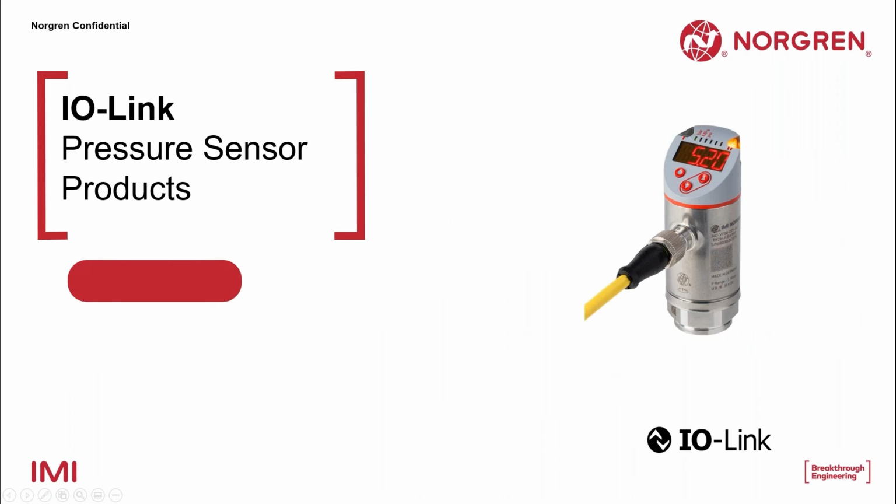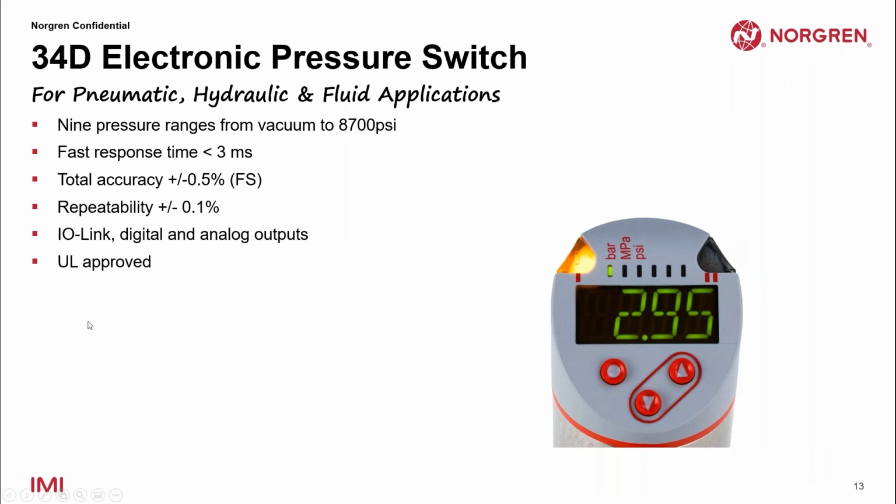Next up is our IO-Link pressure sensors. The 34D is Norgren's electronic pressure sensor and switch. It's available in 9 pressure ranges, from vacuum all the way up to 8,700 PSI, which makes it ideal not only for pneumatic, but also hydraulic and fluid applications.